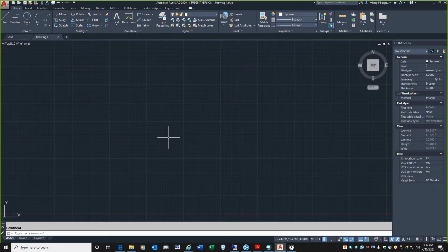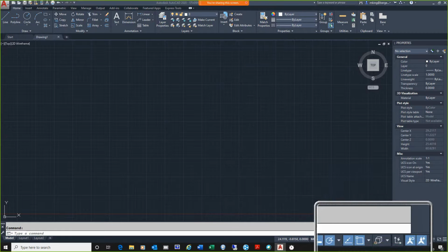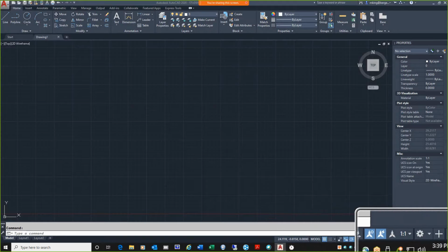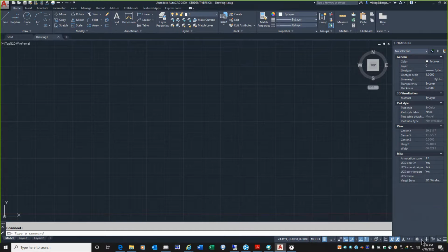So before we go to the 3D workspace, let's resave this so that we don't have any disruption coming back to it. How we do that is down here in your status bar, all of the buttons, snaps and all that. If you keep looking further to the right, there's this little gear button. Okay, this is your workspace button. Select the little white downward triangle, and that's going to open up the list of your workspaces. And you can see that we have 3 of them. Now don't switch to any of the other 2. What we're going to do is save our current first. So select Save Current As.